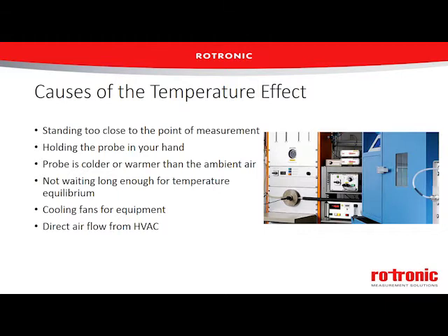So either putting a probe into a chamber right away and not letting it come to equilibrium, or potentially we're a field technician and our probe's been in a hot car or a cold car depending on the season, and we're going into an environment to take a measurement. It's especially important to take into consideration putting a colder probe into a warmer, humid environment, because in that case we'd actually get condensation on our probes. So they would read 100% until the sensor itself dries out.